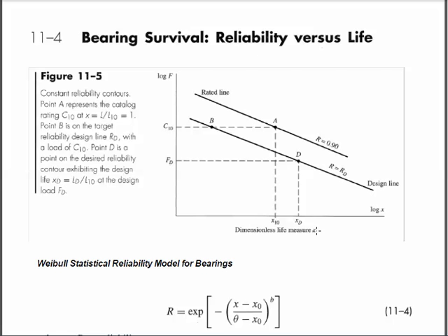And for a bearing rated at 90%, here is how life varies with load along that very same straight line with that same kind of slope. But if we'd rather talk about a bearing with a different reliability, and notice this load went down. Let's say I'd like to talk about a bearing with a 95% reliability. That means more bearings of the batch have to survive to the failure point where we see evidence of fatigue. And if that's the case, then I'm probably going to, I can run bearings at one load to get 90% survival.